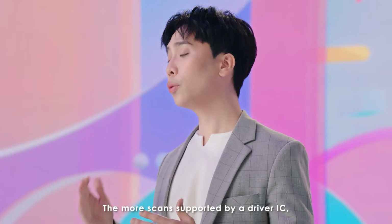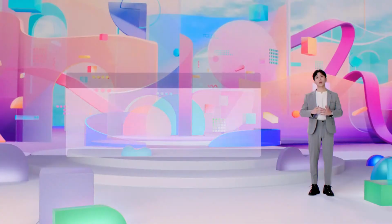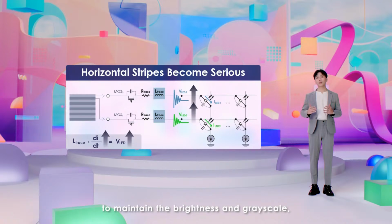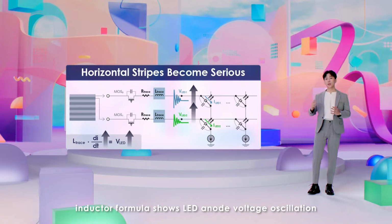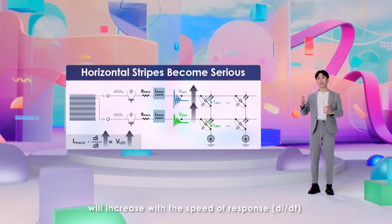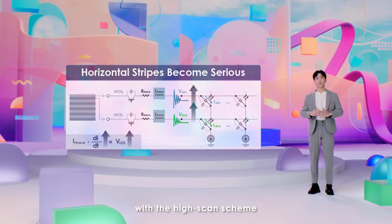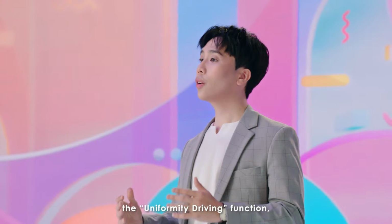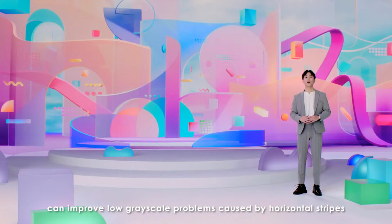The more scans supported by a driver IC, the more serious horizontal stripes will become. As the display increases driving current and speed of response to maintain the brightness and grayscale, inductor formula shows LED anode voltage oscillation will increase with the speed of response. Ultimately, horizontal stripes will be more visible with the high scan scheme. Finally, since MBI5265 is embedded, the uniformity driving function can improve low grayscale problems caused by horizontal stripes.